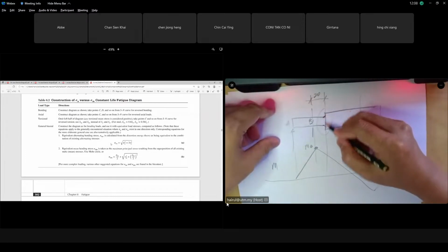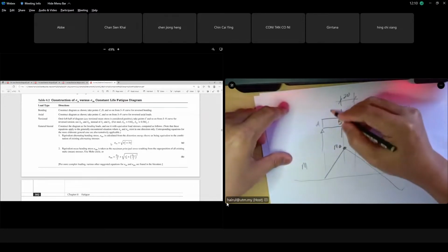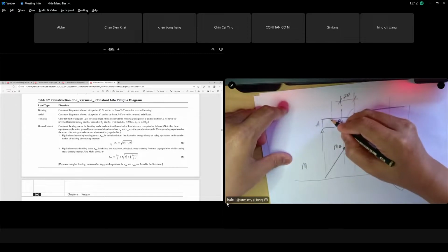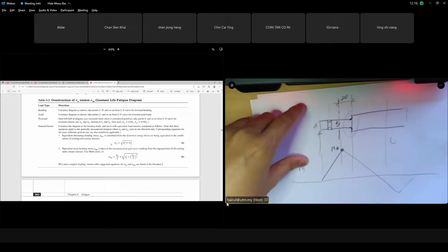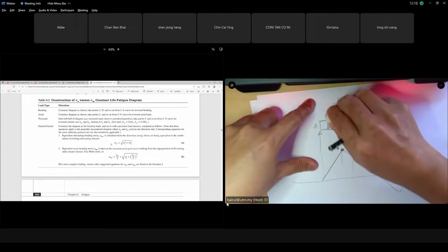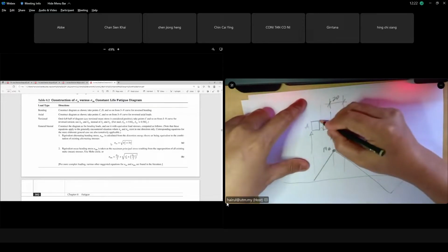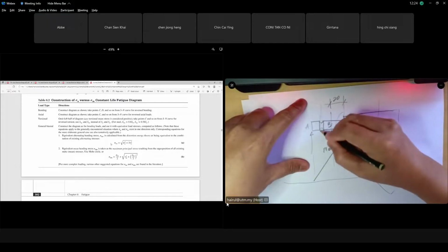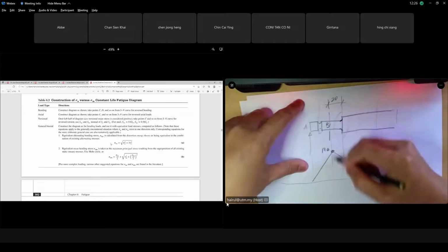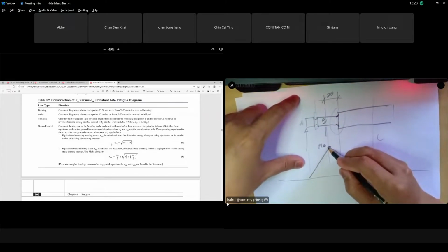Or maybe at some point we have a groove, a small cut in the shaft, where we mount a washer, a snap fit ring, to lock the pulley, because B is where we have the pulley and the greatest moment.